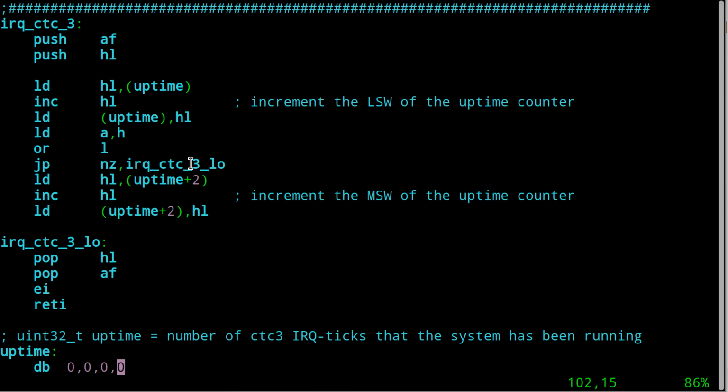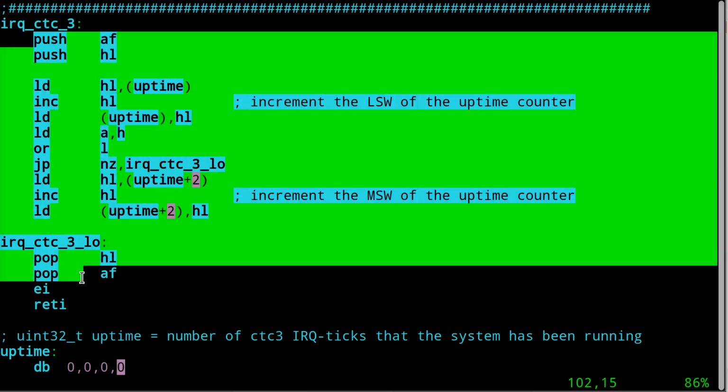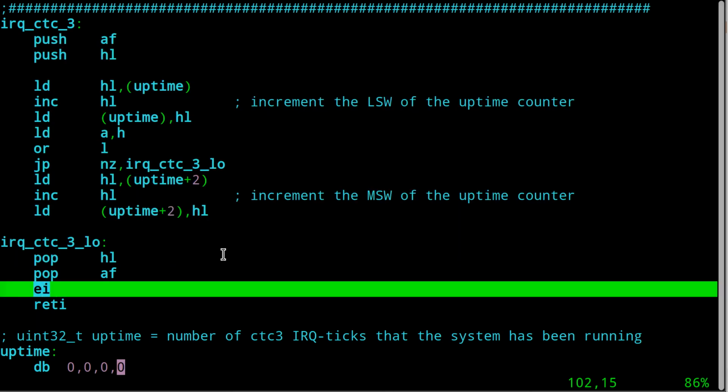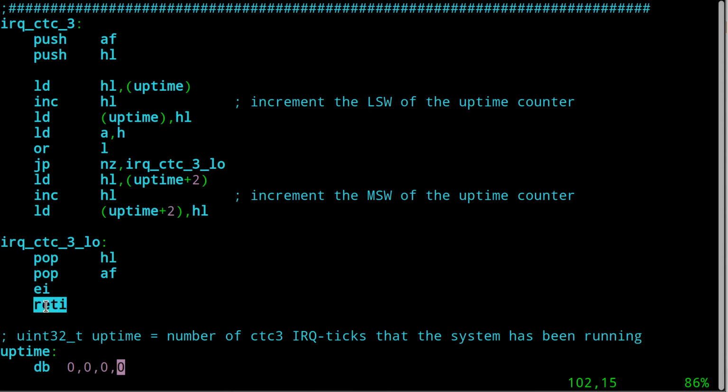In theory, this could actually interrupt itself if you got really creative with your hardware, okay? The Z80 does you a nice favor. By default, it doesn't do crazy stuff like that. It's all up to you to create your own levels of crazy. So when we enter in here, interrupts are disabled. I have to re-enable them when I'm done, is my point. Well, then, in order to go back to where I came from, I don't simply return like I do in a regular subroutine. I have to tell the Z80 that I'm returning from an interrupt.